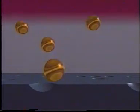Now the ball is removed. An elastic recovery or spring back occurs, forcing the indentation of the ball from its original depth to a more shallow indentation. This stress reversal causes compressive residual stresses to develop parallel to the surface of the dome-shaped depression. Now, suppose a large number of balls are pressed into the surface of the metal, covering the entire surface with indentations.